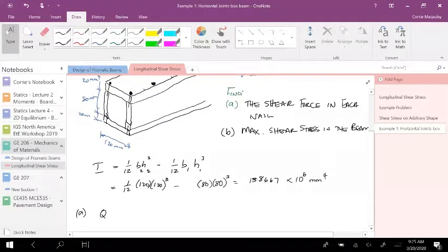Would it be the heads of the nails? Right. So we're looking at shear stress, right? And if this plank is going to pull up, we want to look at shear stress or shear force. And again, remember, it's horizontal. It's a horizontal shear force. So basically, we're worried about...